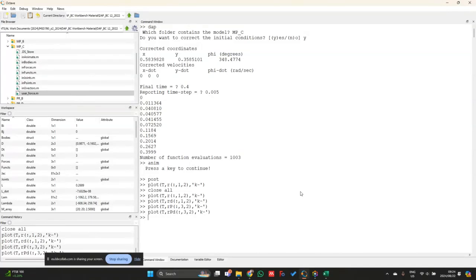If we are, however, interested in the dynamics, so if I'm perhaps interested in what the output force or something would be, then it would most likely change due to the actual masses. I'm currently using massless links, where if I use links that actually have a mass appended to them, then it means I'm going to get different force outputs due to the weights having an effect as well. All right. Okay, so any other questions?